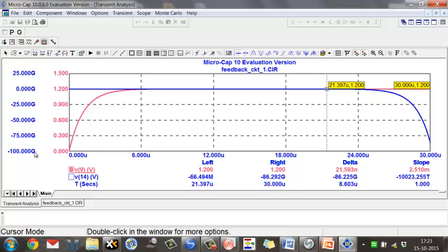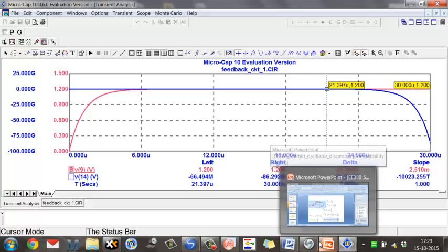In real life, when you go and make the circuit in the lab, you will switch on the power supply, and your op amp has transients in it. It has a frequency response. It has a delay in it. And so you end up getting into this kind of phenomenon. You don't go into steady state directly. You start from some initially uncharged value, let's say 0, and then you go. And then as you go, the differences crop up between the two circuits. So simply doing steady state analysis is giving you the wrong answer. How you arrive at steady state is important.